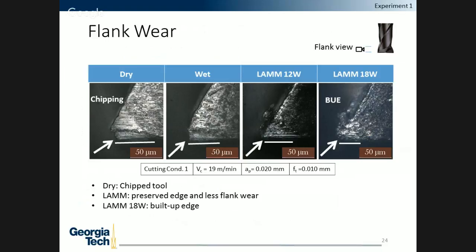Under wet, there was less chipping. There is actually no chipping there, but there is still a fair amount of flank wear. And under the laser assist 12-watt condition, interestingly, it helped preserve this cutting edge. And because of that, the tool wore less and also had slightly less flank wear.